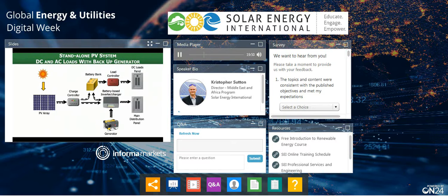Those inverters will have a separate input for the generator most of the time. And so you can have a generator as what we might call an AC input, and the main distribution as the AC output of this battery-based inverter charger. With good quality inverters, we can also do auto start. If we have generators that are auto-start capable, and we usually do once they get into any real size other than small generators, we can tell the inverter to start the generator whenever it needs to charge the batteries at a certain set point.